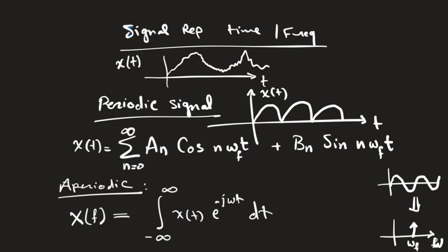So I take that signal, multiplied by, again, this representation. You learned that in your signals and systems, it can be decomposed into just cosines with some phase shift, or it can also be represented as complex exponentials, another representation, right? Starting from that complex exponential, if you see that your signal becomes more and more aperiodic, so the period becomes larger and larger such that it becomes almost an infinite period, this summation becomes an integral, and you end up with this representation.